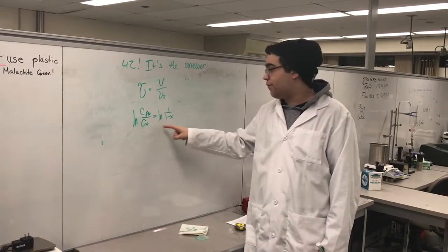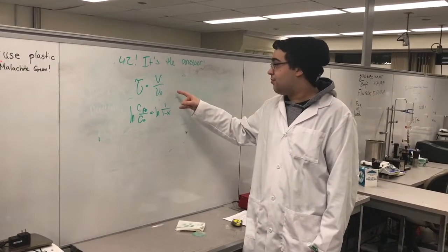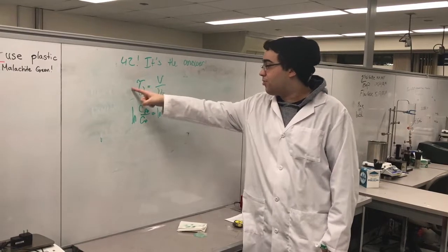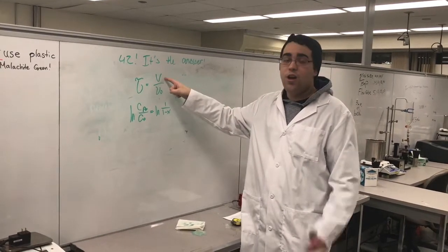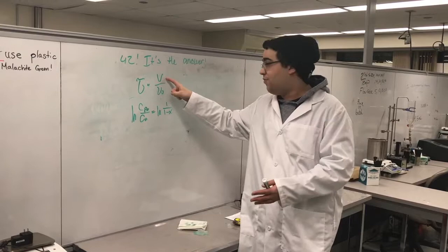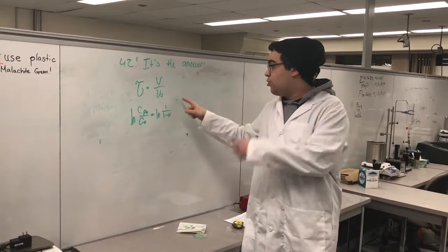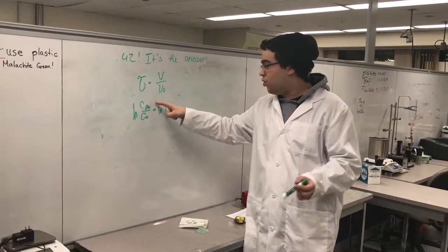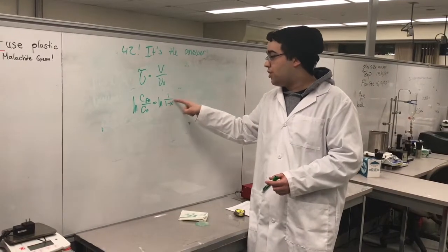first order PFR conversion equation are key for defining our system. Increasing the length will see an increase in the residence time due to the increase in volume, ideal for our system as it maximizes diffusivity. Knowing this, using our final results in the values we know for Ca0 and Cf, we can solve for X